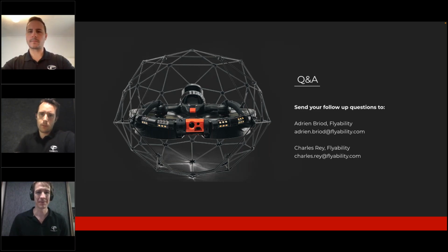Yeah. But remember, it's a mobile mapping solution. So it's definitely not the same grade that you can obtain with a terrestrial LiDAR. That's for sure very important to understand. There's no way. We're talking about centimetric precision, while the terrestrial LiDARs typically are in the millimetric.